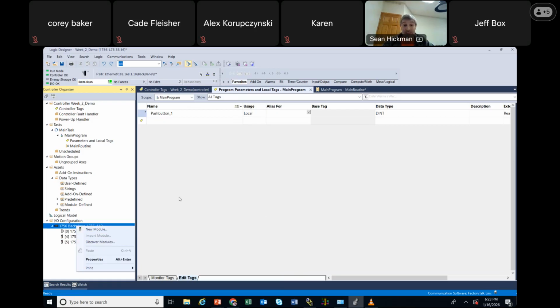Get this, ready? Once you go on and discover everything for the PLC that you're at, do a File, Save As, PLC template. And then every time you start a new lab, just open that up, rename it as lab 10, then rename it as lab 11, then lab 12. That way, every time before you start setting anything up, at least your IO is all set up. That's a pretty good idea, isn't it? Or you could set it up every time. Yep. Oh, that is smart.